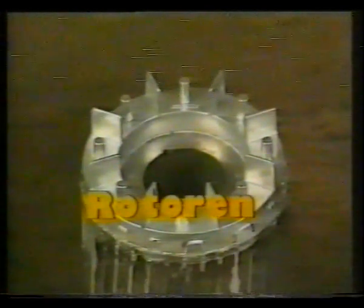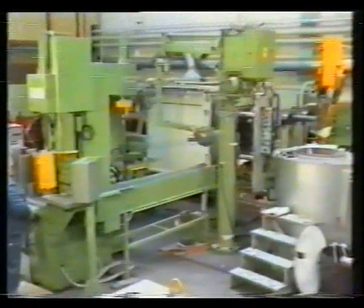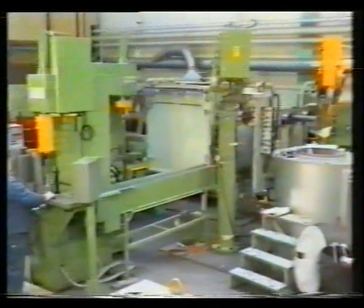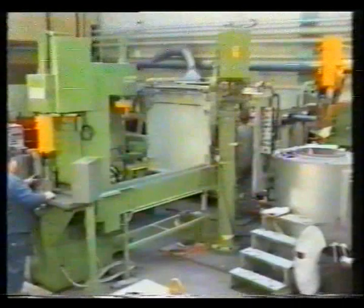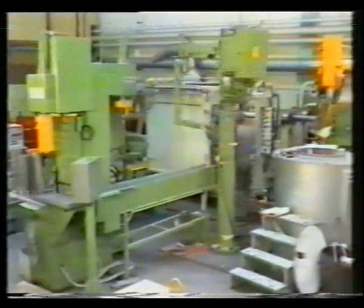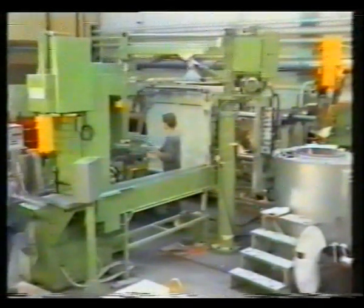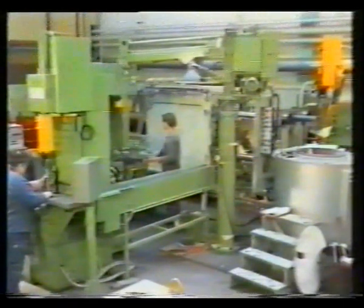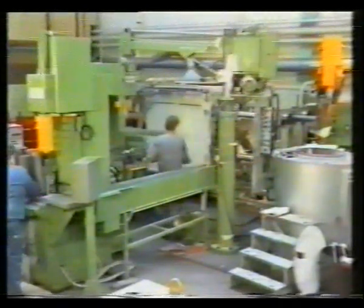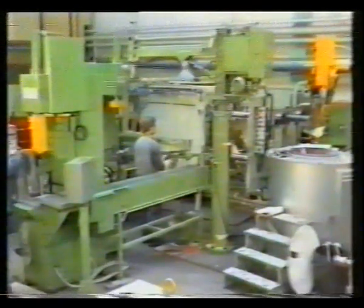Rotors. Production of 2, 4, 6, and 8 pole rotors is performed by 2 die casting systems in this project. With shaft heights of 56 to 90 millimeters, 2 impression dies are used, and the locking force is 2,500 kilonewton. With shaft heights of 100 to 160 millimeters, single impression dies are used, and the locking force is 4,000 kilonewton.